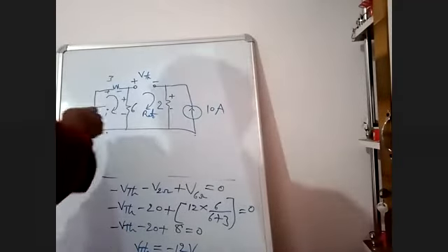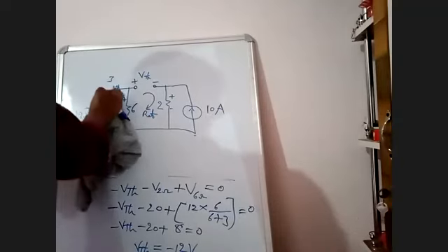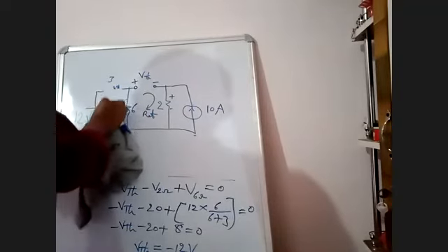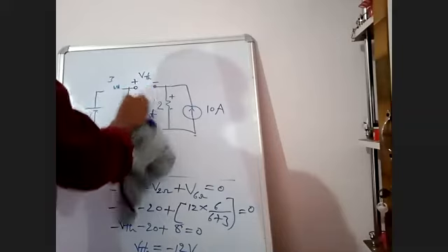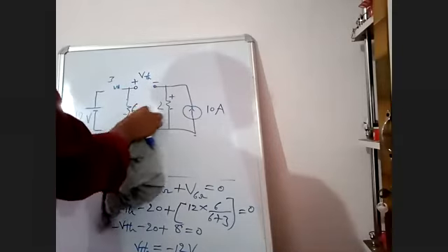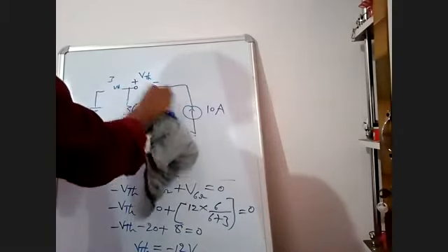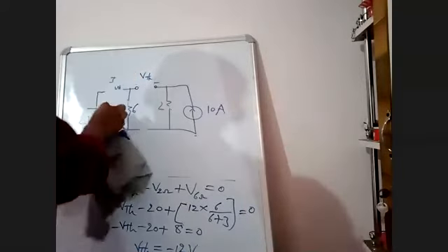For RTH, what we will do? Short circuit all voltage sources and open circuit all current sources.